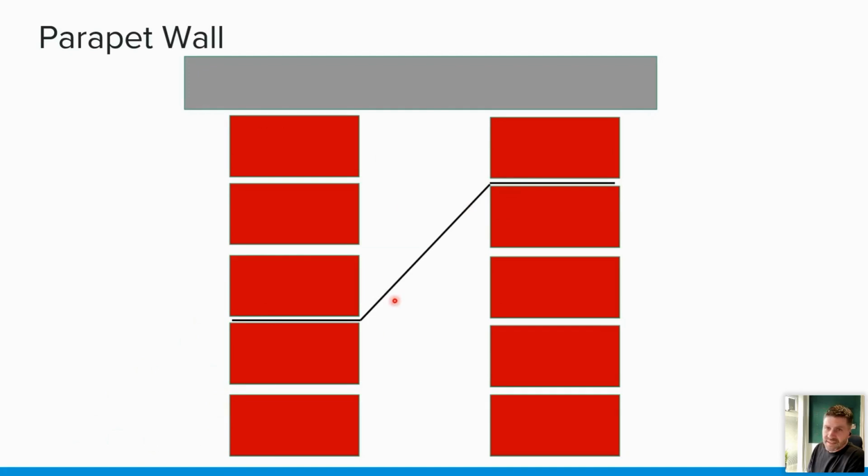And the way of doing that is if the parapet wall isn't too high, we can take this coping stone off. Obviously we need to look at the heritage of the building. Is it a grade 2 listed building? All of those kind of things. But can these coping stones be removed? If they can, then we can take the waterproofing. We can put a cavity closer on here, get rid of this coping stone and take the waterproofing up and over here, and then finish it on a drip or a check or something like that with a trim on this outside edge. And then what we've done here is we've waterproofed straight across here, and we've made this cavity tray redundant. So then it doesn't matter if we're blocking up these weep holes.